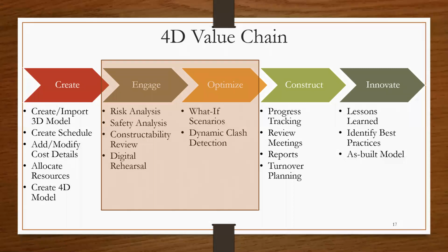Digital rehearsals is essentially looking at some of the complicated processes or events that you expect during the construction stage, and simulating that to help you identify additional risks or additional mitigations that you need to take to accomplish that quickly and safely. This is one of the key advantages of a 4D model.